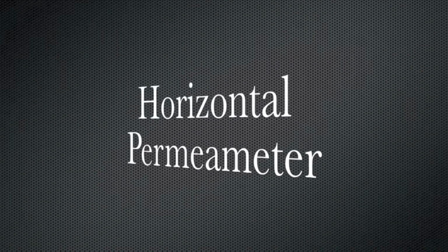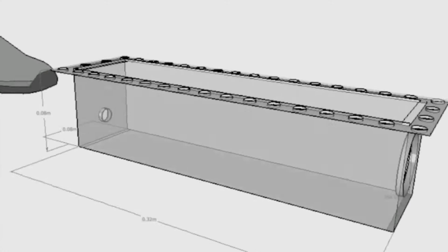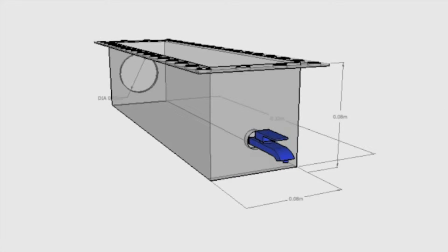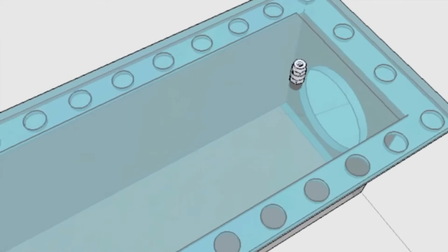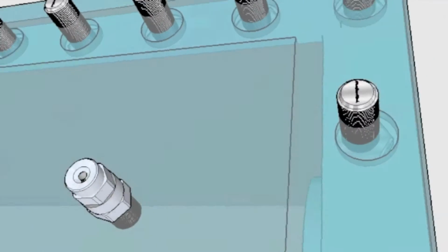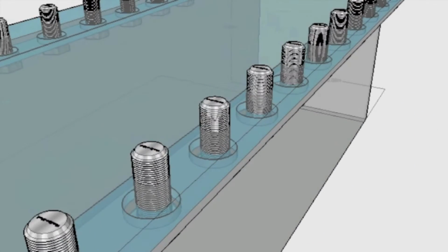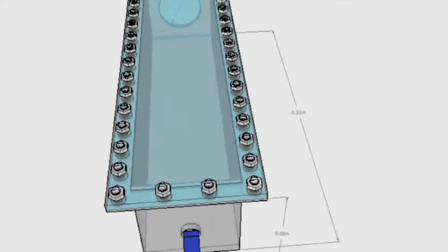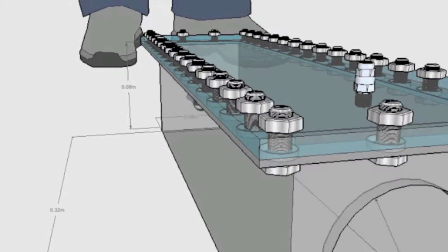The horizontal permeameter was designed just like the vertical permeameter. It's made out of acrylic glass for good interior visibility, has its own outlet for drainage, and a top cover for confining. It also has a vacuum tap to de-air the sample before testing. It has numerous bolts and of course nuts to seal the sample when saturating. Of course, there is no saturation when there is no water.